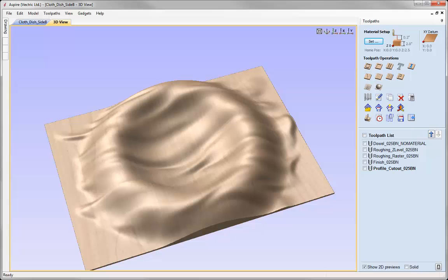For the toolpaths, we followed a pretty typical two-sided machining method. The biggest thing, as I've mentioned a few times here, is the fact that because of the depth of this model, it's important that if you do it exactly as I've shown here, that your tool has at least 2 inches of clearance and 2 inches of flute length on it when you come to cut the part. If it doesn't, it may not cut properly, and the collet of your machine or the collet of your spindle or router may collide with the material while it's cutting, which is obviously very dangerous and certainly, if nothing else, would damage your part.